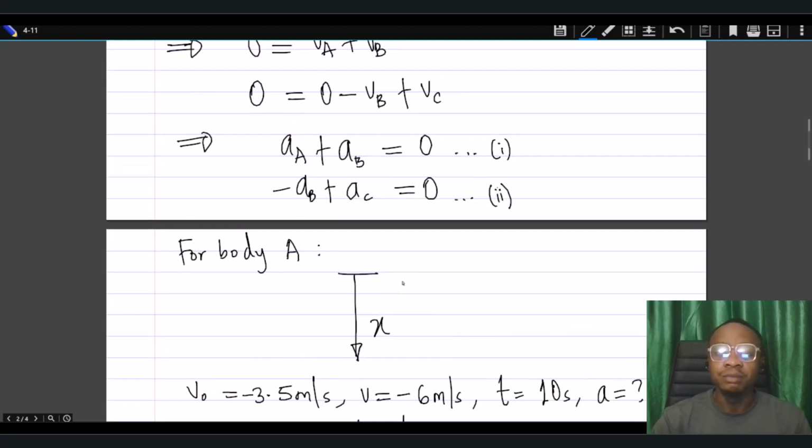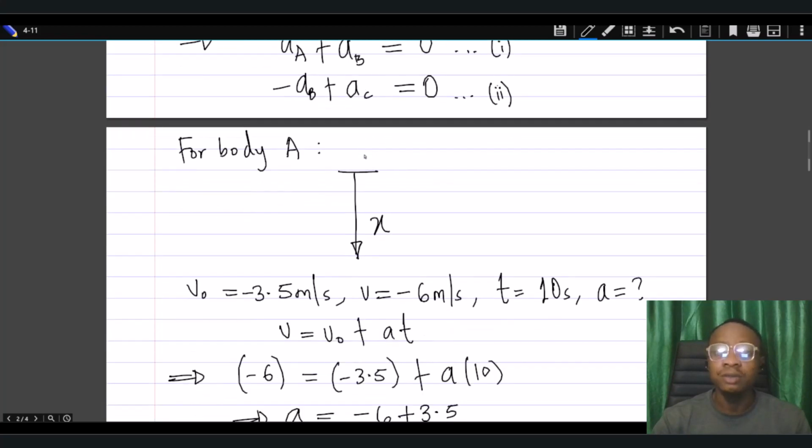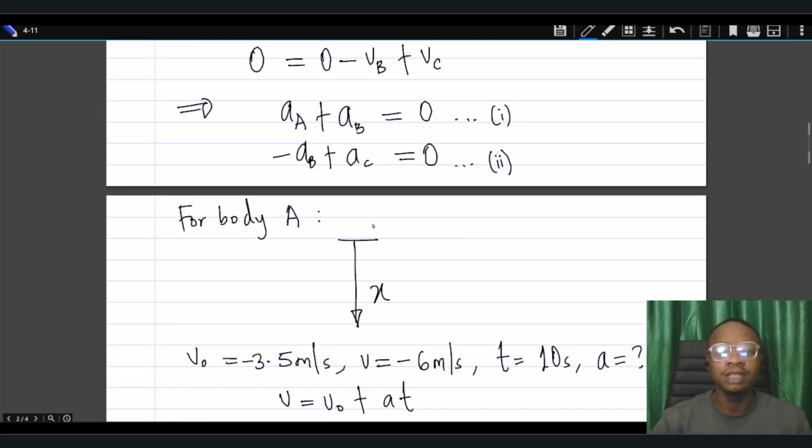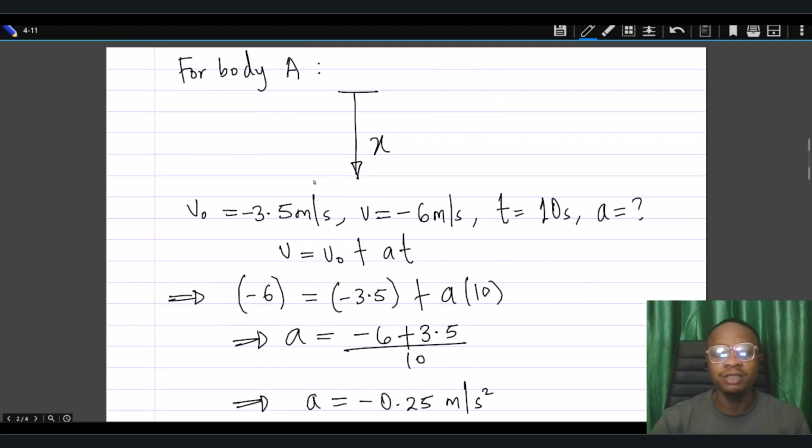And if we brought that into this set of equations, we will get completely wrong answers as to the signs of these accelerations. So that is the problem we have avoided completely by just sticking with the coordinate system we have so defined. Okay, and so making use of equation 1 now, we can make substitutions so that we obtain the acceleration of B, and then equation 2 to obtain the acceleration of C.